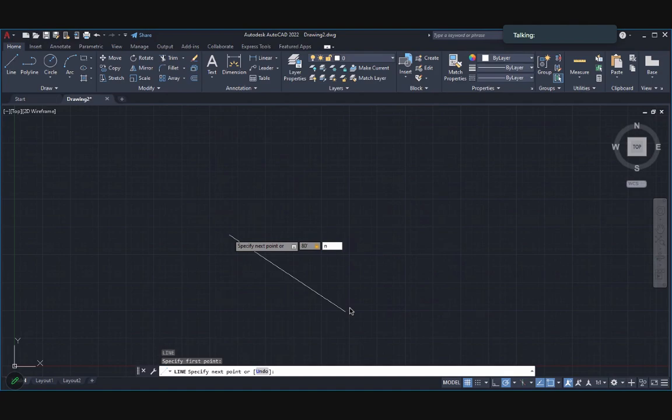And then no spaces, you're going to put in 71, and then for the degree, you're going to put letter D. So N71D, and then you're going to put 30 for 30. Minutes is just an apostrophe. And then 0 for 0 minutes, and for seconds, you're going to put in a quotation mark. So that's how to put it in.